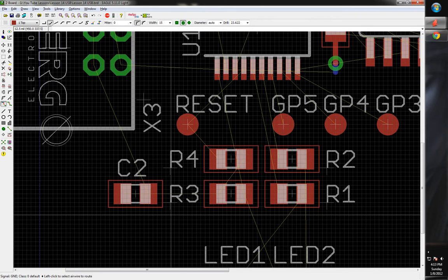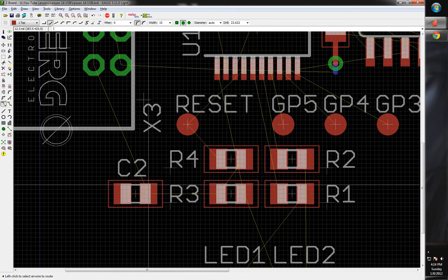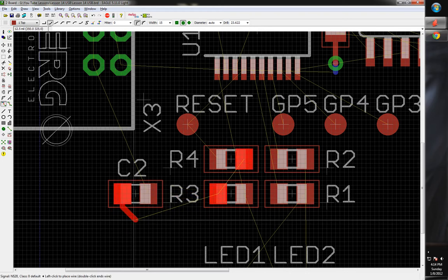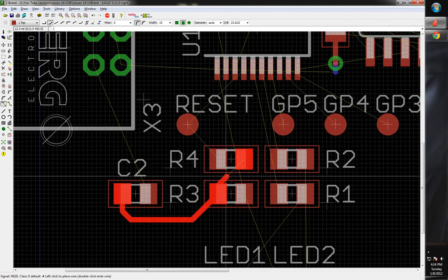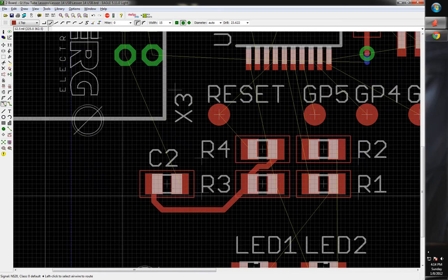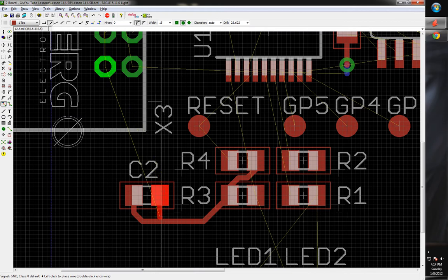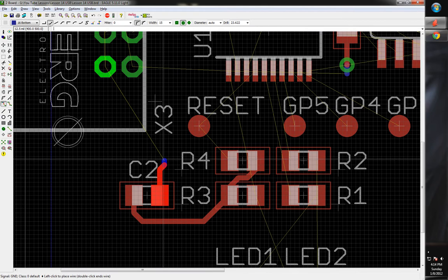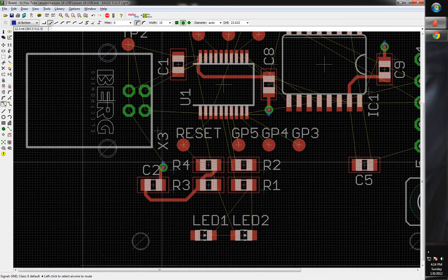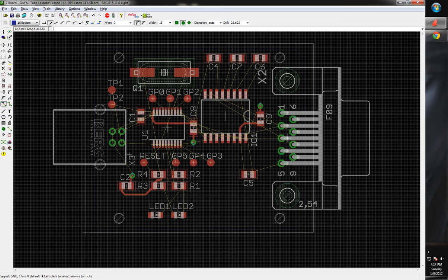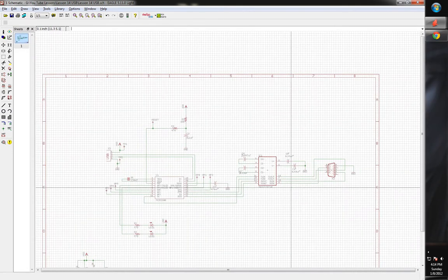Its ground is up there, which is fine, but it looks like it's going to connect to these guys. We can just go ahead and connect these guys up if we wanted to. There we go. Got those guys. We can just do the via thing if we want. Escape. Okay, there we go. So that grounds all that. Is there any other decoupling caps that are very critical? These I placed close enough that they're all going to go to that IC just fine.